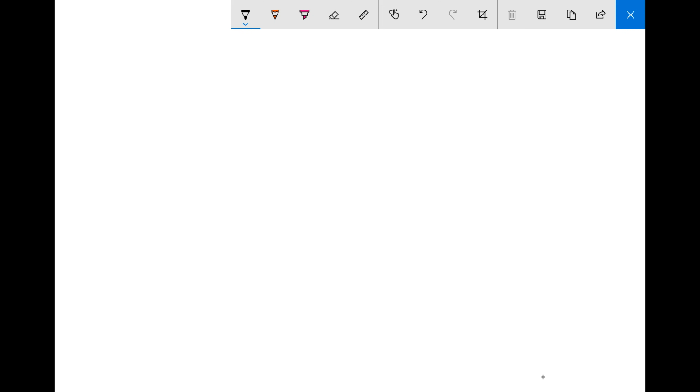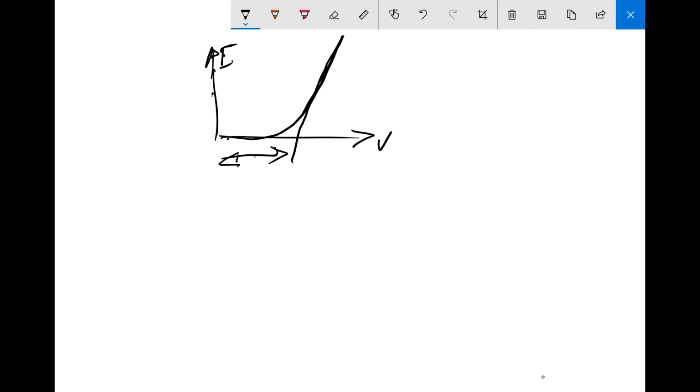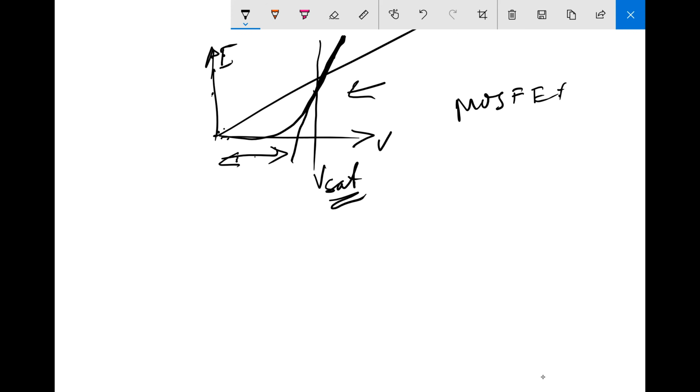On the other hand, in a BJT, very typical, you will see something like that. That is, this is voltage, and this is current, which means that you start with a sort of a break point, and then this slope corresponds to very low resistance, and the voltage drop does not change much, the saturation voltage as it is called. And so IGBT will have typically something like that, while MOSFET, as I've said, will have something like that.